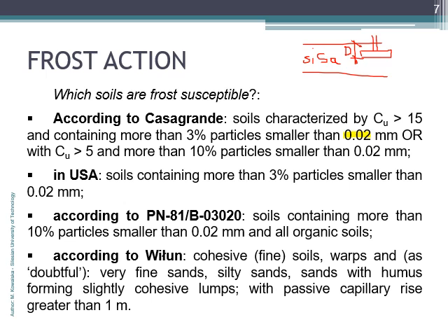But if instead of this case, you have a first layer made of clean gravel, then gravel is not a frost susceptible soil. So it means that you do not have to put your foundation at a depth greater than the frost penetration.